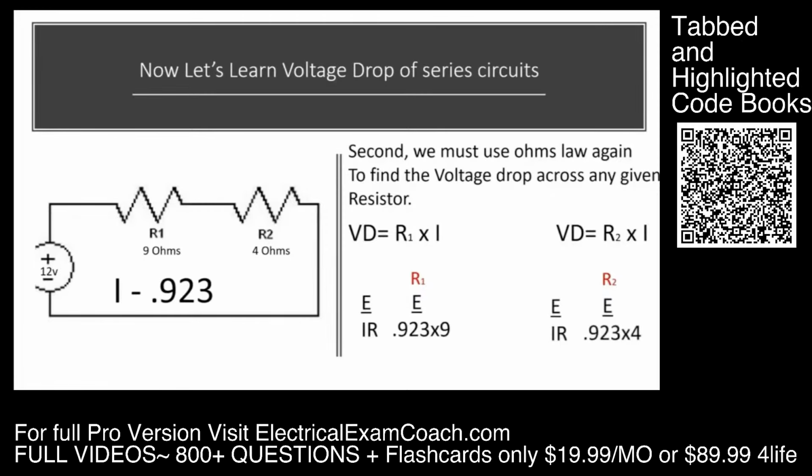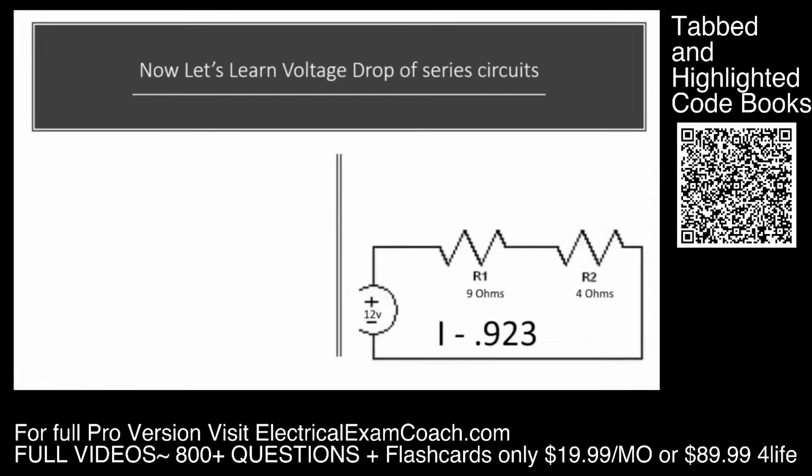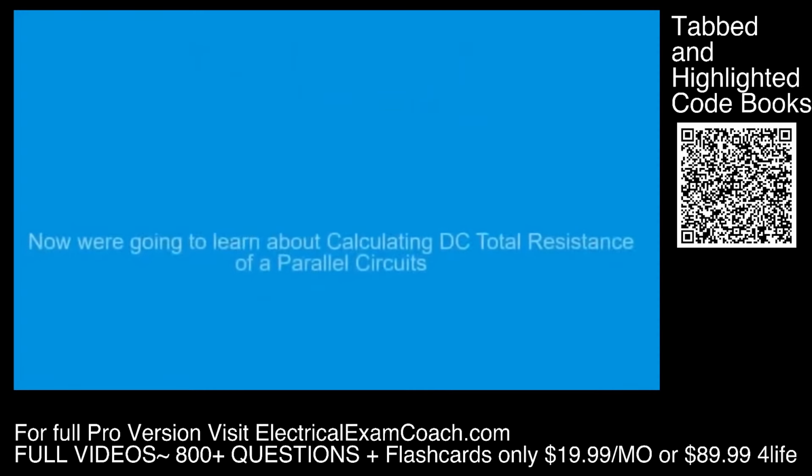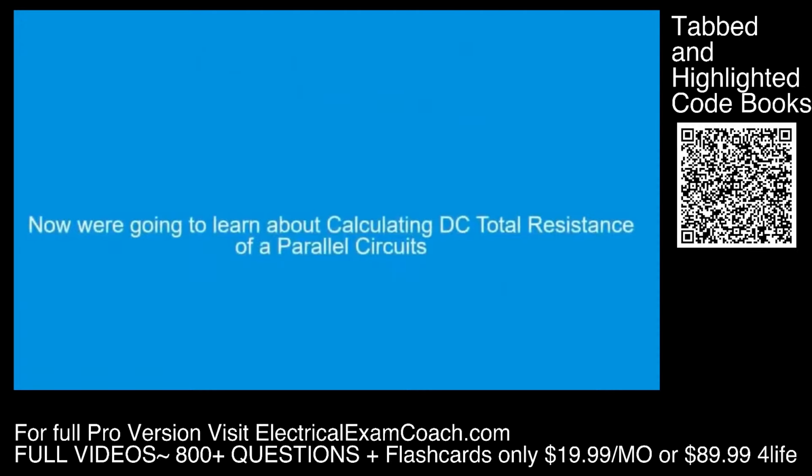On this other side here, we just plug in the knowns, and we know the amperage and the resistance, and we just multiply that, and that's going to give us the voltage drop. So the voltage drop of R1 is 8.3 when we did our multiplication, and the voltage drop of R2 is 3.7. Okay, a quick recap. The voltage drop of R1 is 8.3. The voltage drop of R2 is 3.7. 8.3 plus 3.7 is going to equal 12 volts. The voltage will be equal to the sum of the voltage drop across all resistors, and that's how you double check your work.